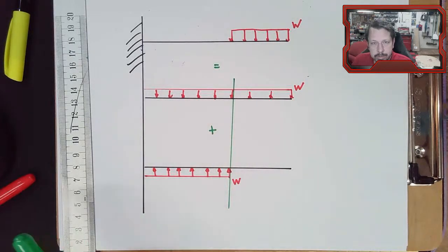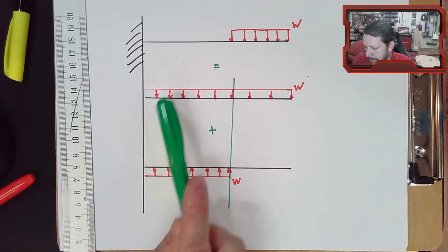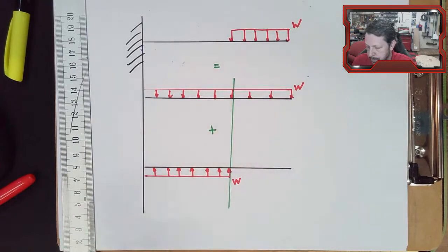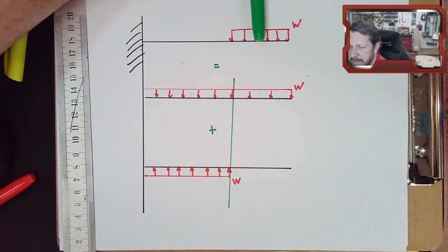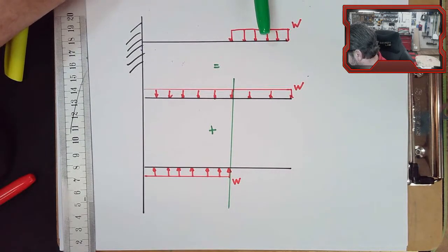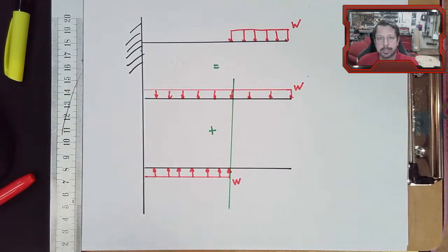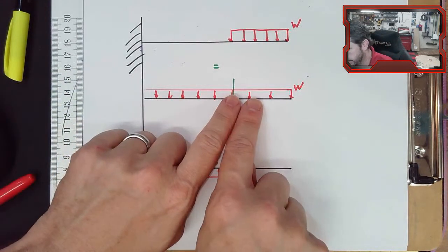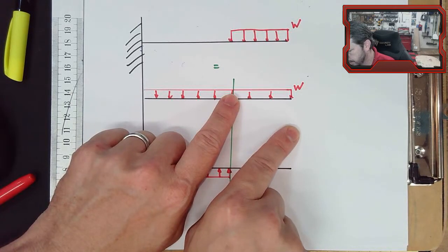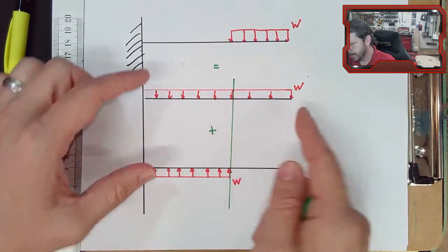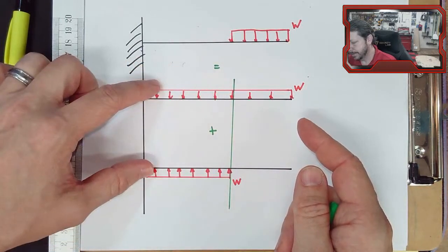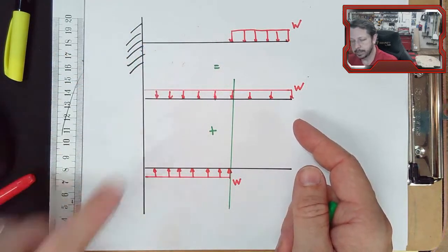So that one is harder to be intuitive about how to figure out how to deal with this. Most people's intuition is going to be put a lumped load in the center of that and do case 1 just like we did the very first example. And that will get close. So as an estimation, that's probably simpler to do, but this would be a more correct way to do it so that you actually get the effect of this beam continuing to curl down under the distributed load, and then you nullify or negate the fact that there's no distributed load in this section.